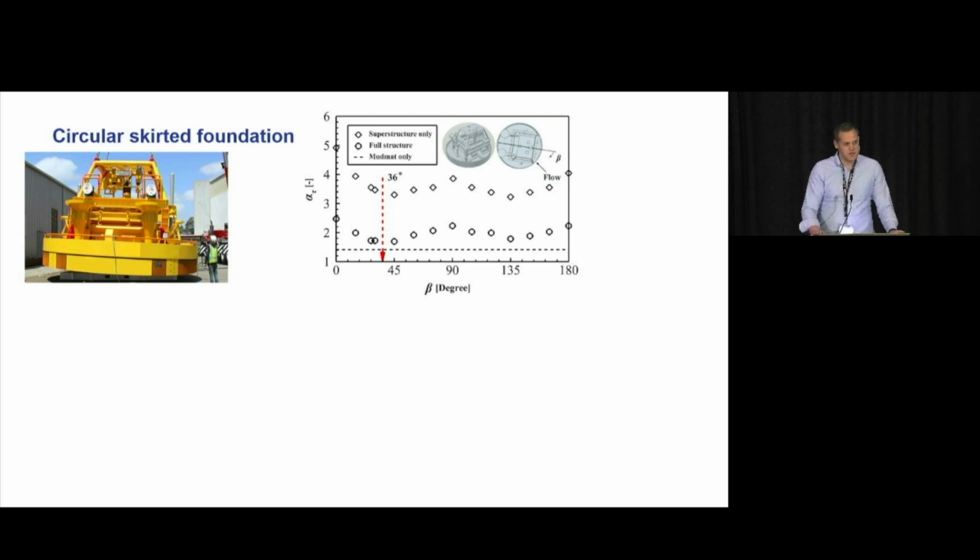This is how much the shear stress is increased local to the structure compared to what it would be in the free field. If you have a big amplification factor, it's very easy to get scour with a very small flow, because the shear stress is amplified so much near the structure.